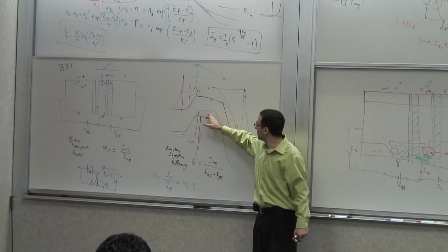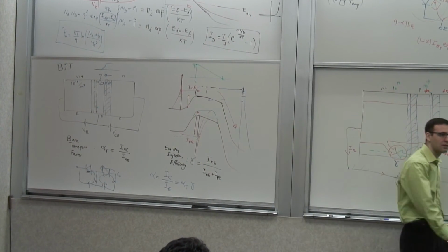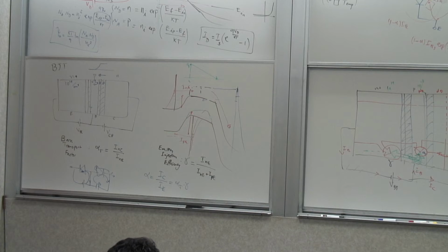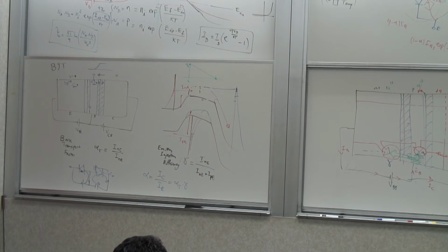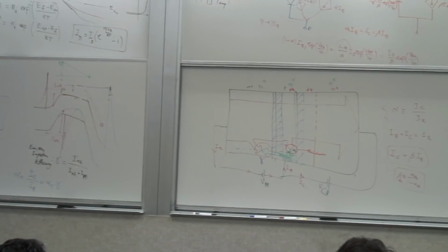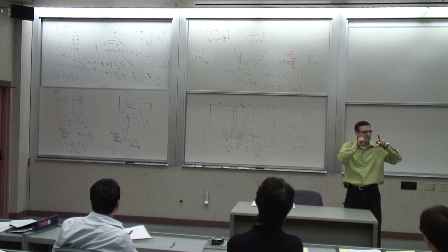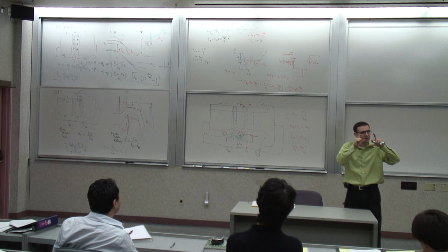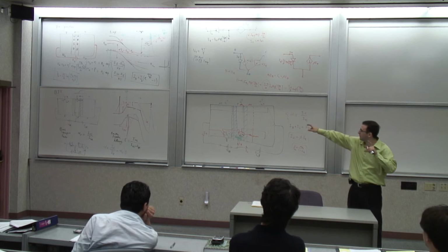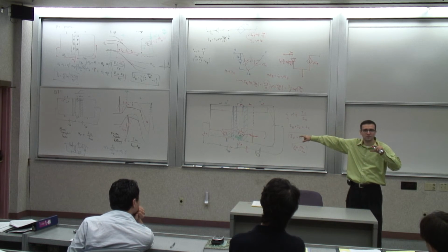Do you think it can help or hurt us? Just the way you've done it, what did it allow you to do? What we did is to increase the potential barrier height for the holes only, right? So for a given doping level, it gave me a higher emitter injection efficiency, correct? Higher gamma.